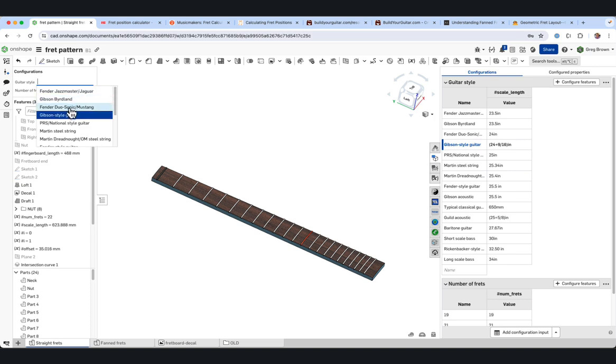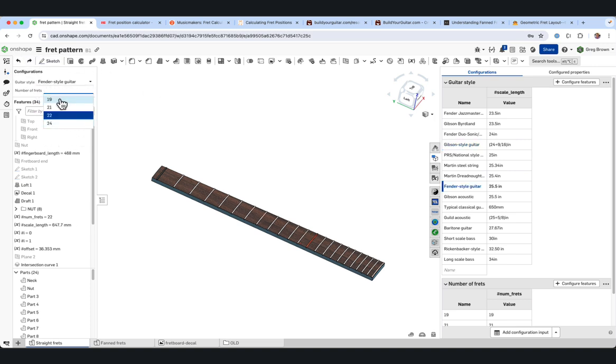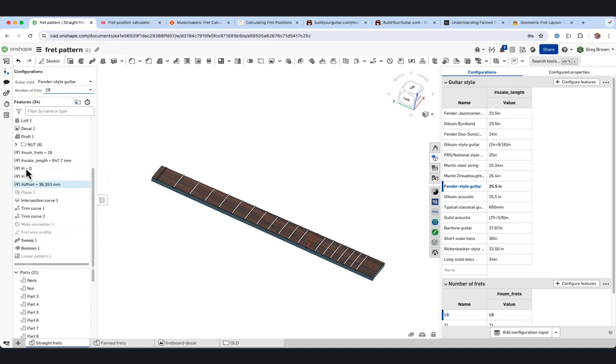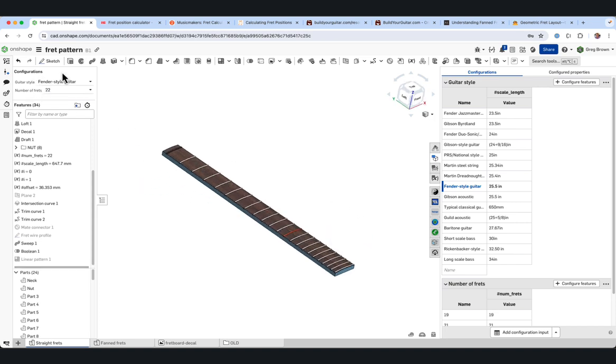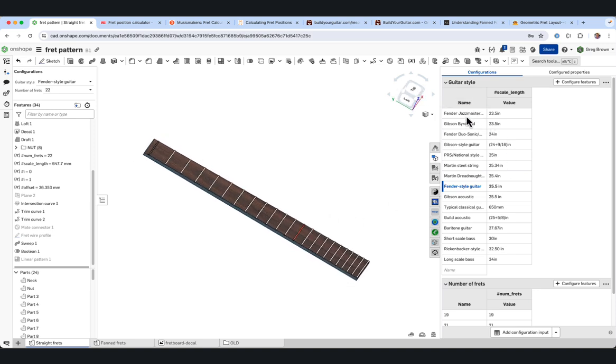You can also change the number of frets. Now, most of these guitars have between 19 and 24 frets in this. So, that's obviously just changing one of our key variables here, which is the number of times we would iterate this loop in our for i loop here. So that's not exactly rocket science, but it's really easy to create a nice configurable situation here in Onshape, and give them a nice name. So very good, very good.